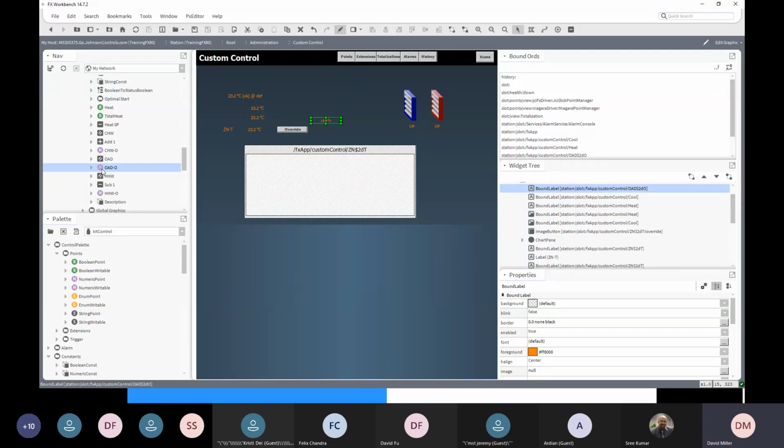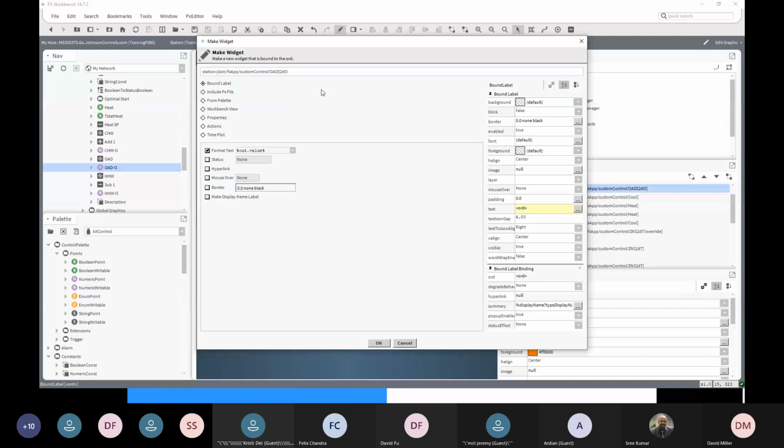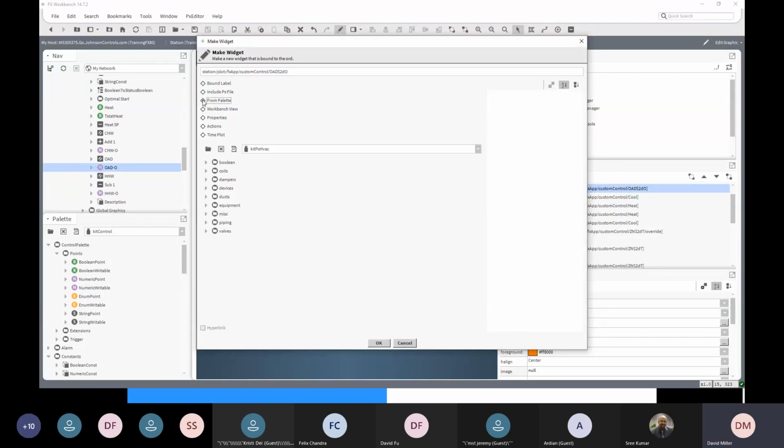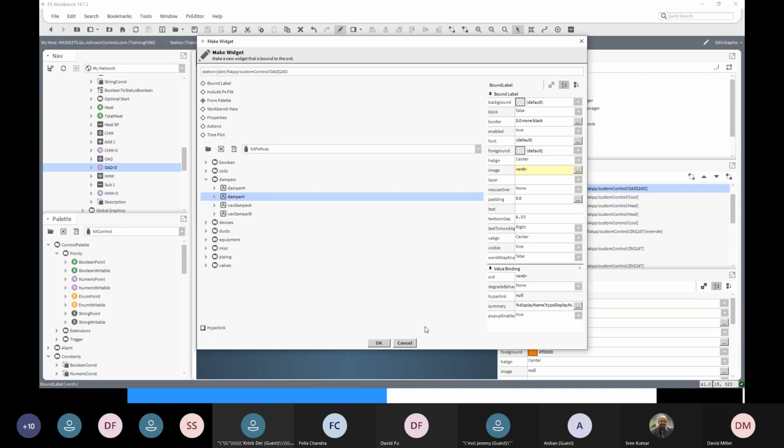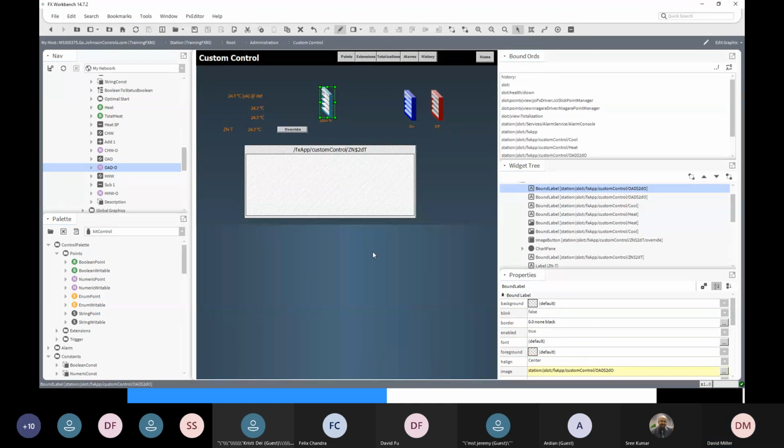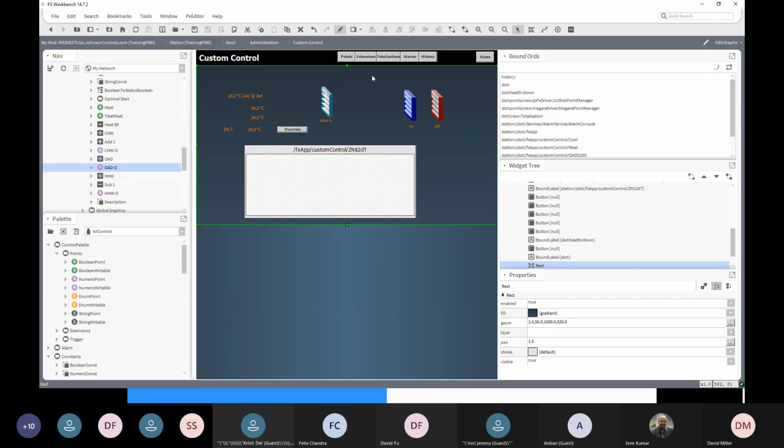If I bring that outside air damper in again, but this time from the palette I choose damper vertical, and go OK. There's my damper. Okay, so 100% outside air, the cooling's just turned off, the damper's starting to close off. Opening back up again, cooling's come back on.